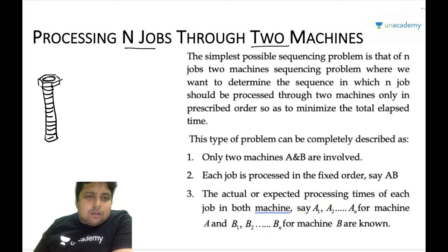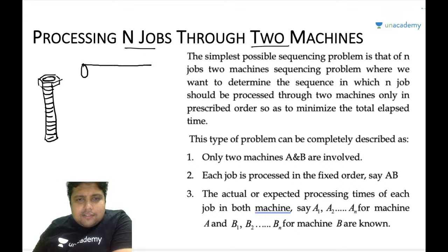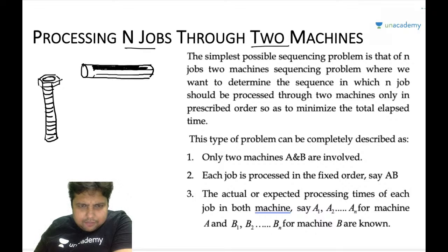Okay, so if I will manufacture this bolt, what I will be doing, let's say I will take a solid shaft, and then via the turning operation, I will simply turn out this much material that I am shading in black color. I will simply remove away the material that I am shading in black, and then, let me do that in red color, via performing the threading operation, I will provide thread on this bolt.